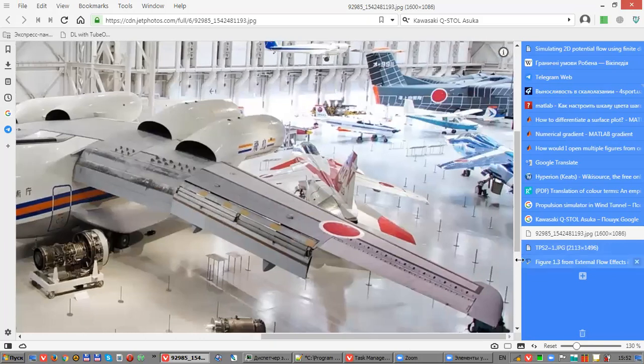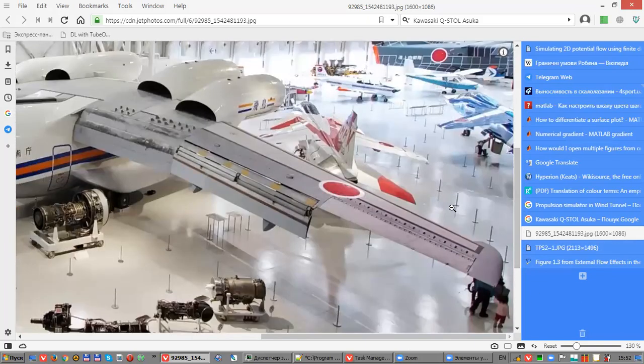We have an aileron here, the outer section of the wing and the inner section. Yes. And in the outer section there are also vortex generators. These small dots are the same device, but not so big as this one. This is very big, this is smaller. And when you look at the wing of the Boeing 737, there are also small vortex generators. And these vortex generators increase the efficiency of the aileron at high deflection angles.